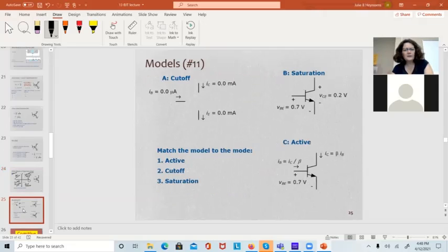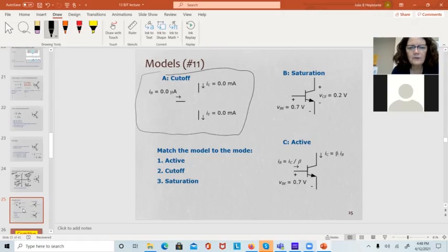So I've got models of the transistor in the 3 different regions. This is my favorite. This is cutoff. I went ahead and labeled them. In cutoff, no current flows, or just leakage current, and that leakage current can be like attoamps. Most people don't care, but astronomers. IC0, IE0, IB0, and the transistor just looks like a big open circuit.